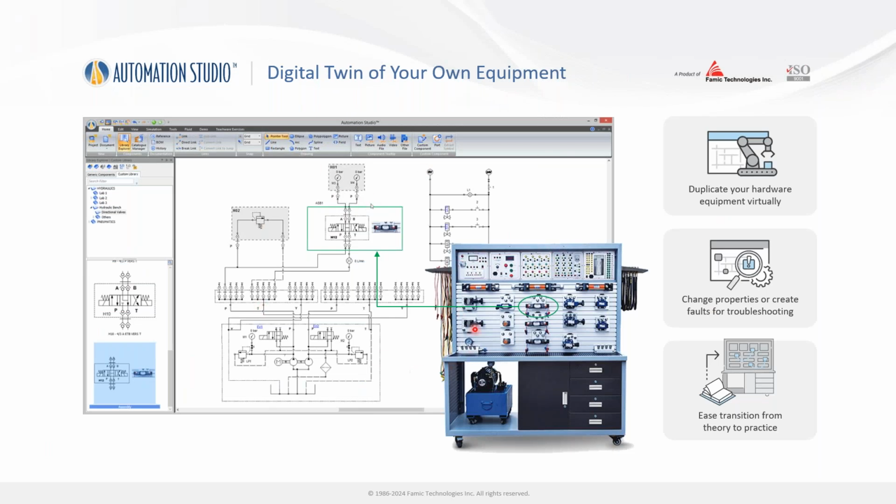So you need to just make the connections with the help of jumper wires that we have in the electro hydraulic trainer kits. Once the connections are made, and once you establish a connection with the help of OPC, that is Open Platform Communication, on the one hand you will be having the Automation Studio software. On the other hand, you will be having the electro hydraulic trainer kit, and the intermediary bridge acting will be the OPC connection, that is Open Platform Communication.